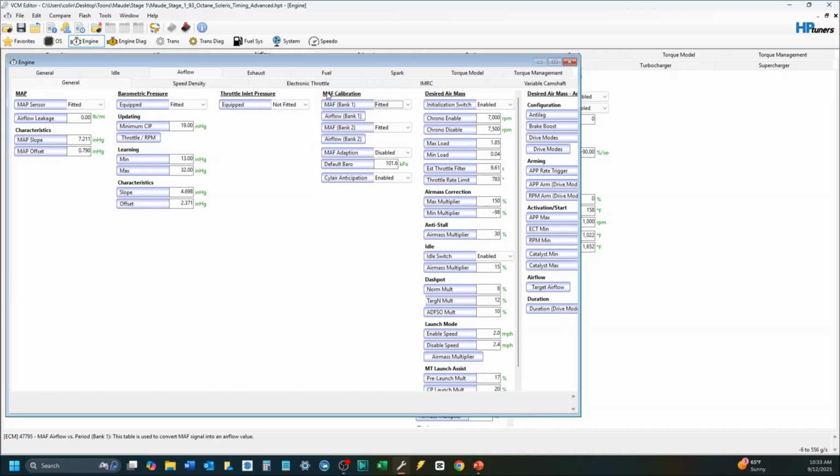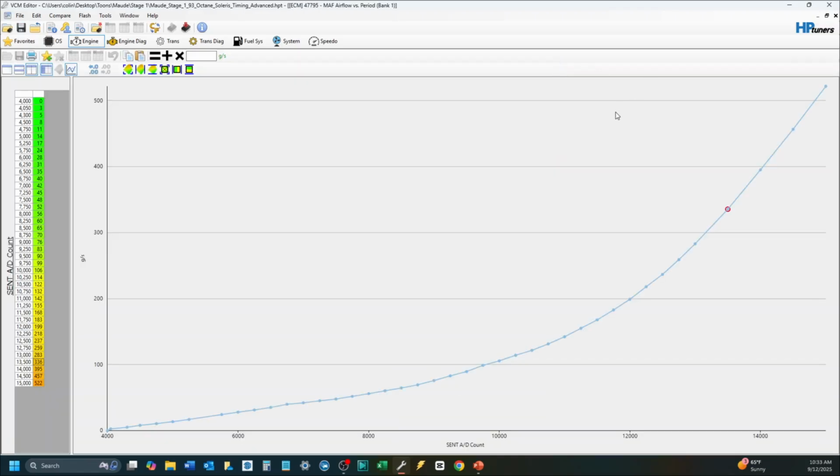And within the airflow bank, we see, as this loads, a familiar shape, right? That's one of the things where if you know how to tune, you can tune a lot of different vehicles if you understand the theory of what a mass airflow curve looks like. This happens to be the one on the S650, and you can see it's got this curved shape, right?